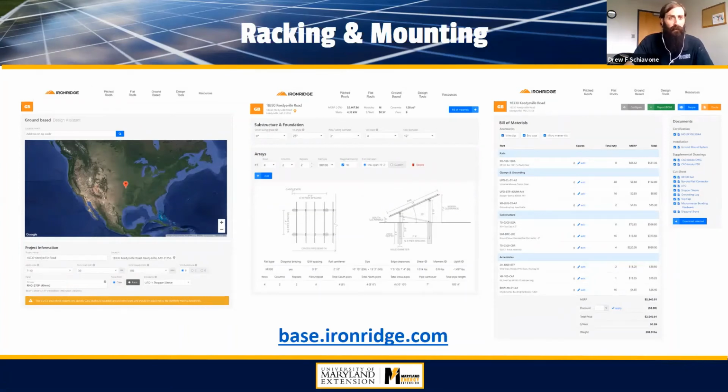I just went to the website for the city I'm in, and I found that I think it was 30 pounds per square foot, yeah, 30. So I put that number in manually. Again, the snow load and the wind data is going to be a code issue, a local permitting issue that you kind of need to evaluate at a local level. But I put those values into their system.